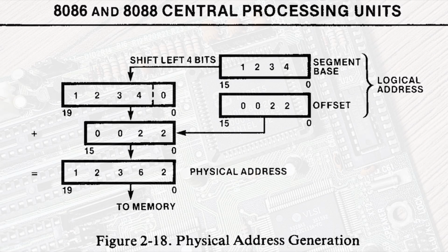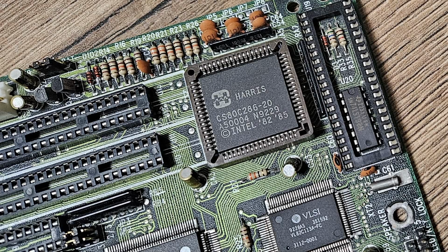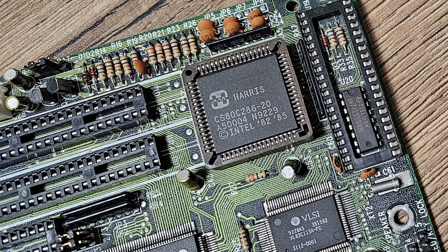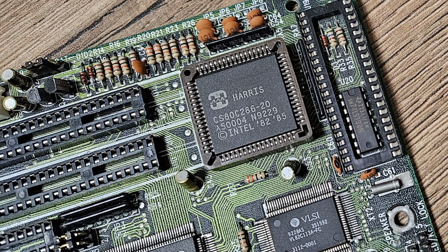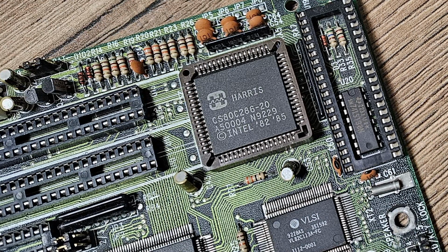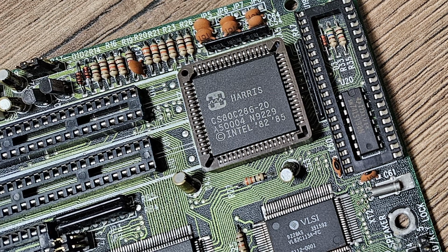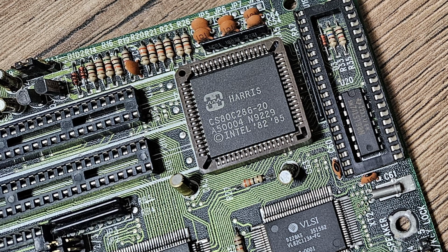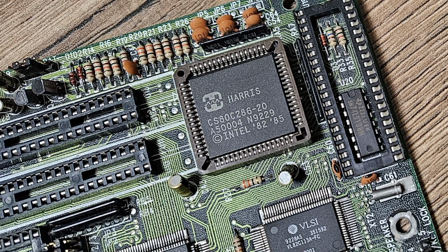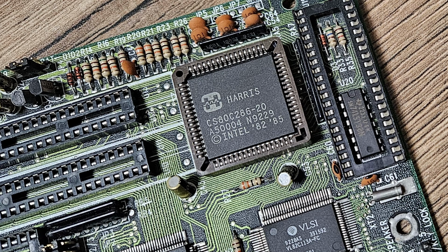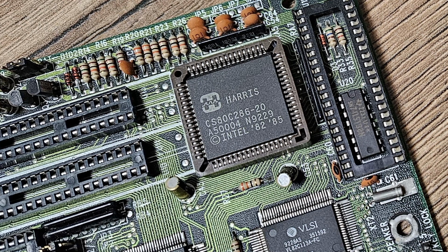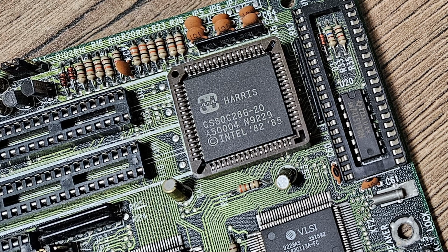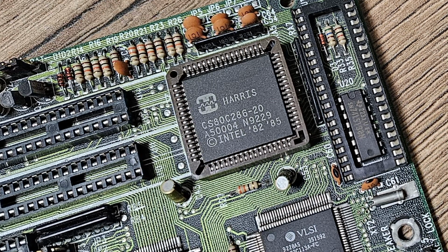Intel introduced 80188 and 80286. From now I will just drop this 80 from the beginning, so the 186 and 88, when they were introduced, they were not compatible with the PC, since the DMA and other port assignment were not compatible with IBM PC addressing. This is the reason why you cannot find frequently those in any kind of IBM PC or PC compatible. But the 286 found its way to IBM PC, so the IBM PC/AT, but I will talk about it later.